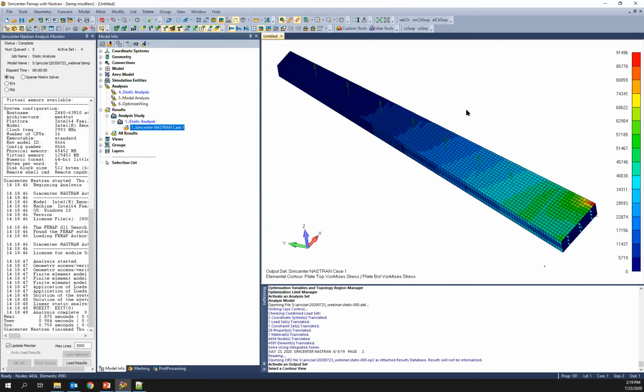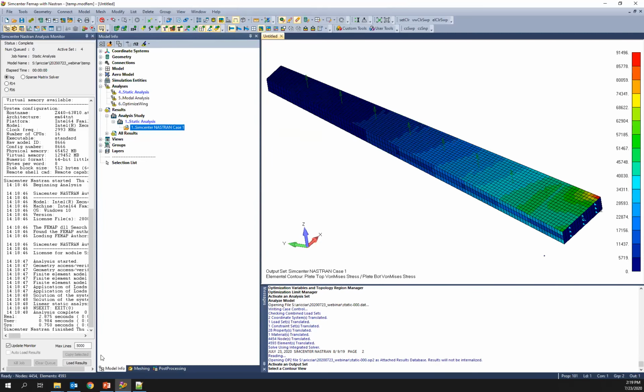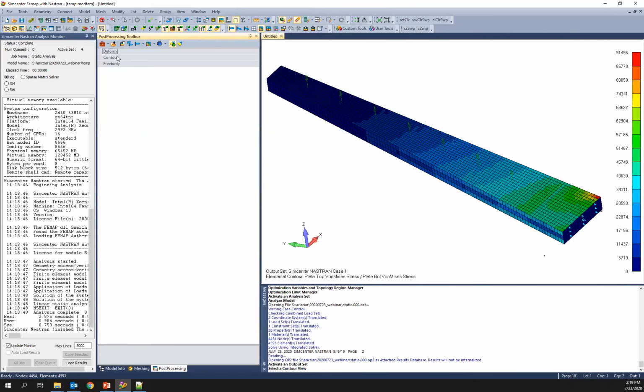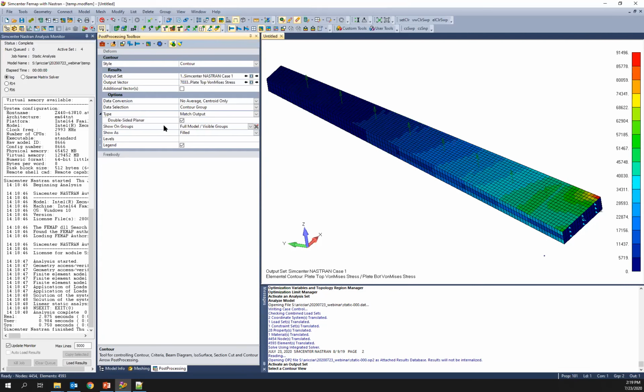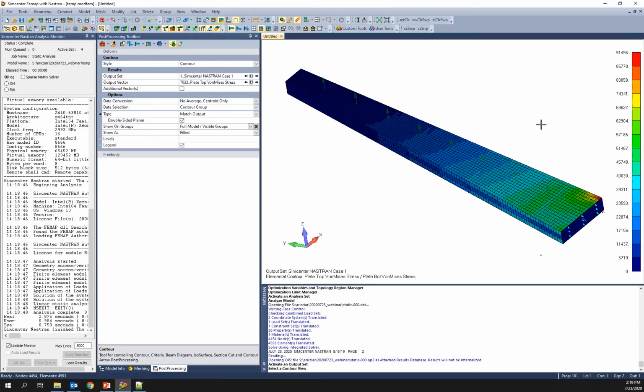So what we see here, these are stress results. Let me double check my view here. So it's von Mises stress. I have double-sided planar check, so it's showing top and bottom von Mises stress on the same results. And what I see here is I have 91 KSI. So I'm horribly violating my constraint around this corner.